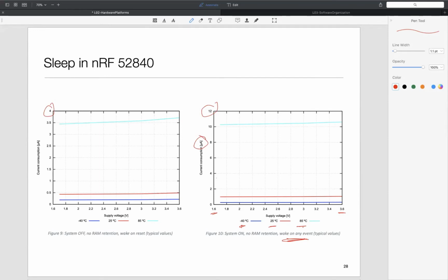So as you're going from left-hand side to right-hand side, your power consumption is going up quite significantly, almost a factor of 2.5 or so. Oftentimes you see data sheets just report the current number, and people just use that as an indication of power. But always remember, voltage matters. And there is a slight dependence of current on voltage still.